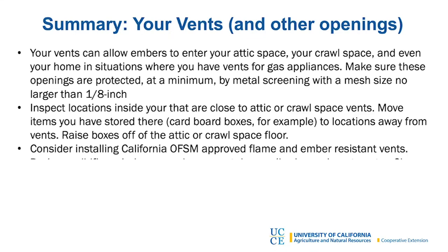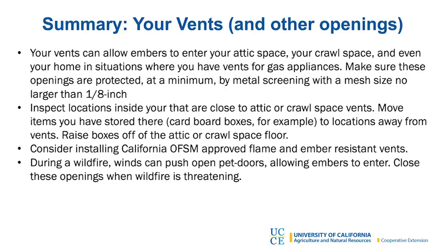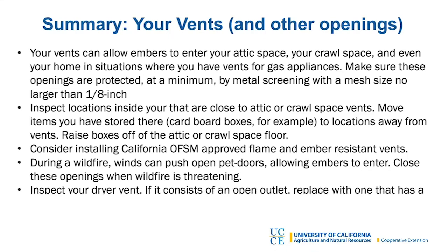During a wildland fire, remember that winds can push open pet doors, allowing embers to enter. So close these when wildfire is threatening so that they cannot operate. And then finally, inspect your dryer vent. If it has an opening that is open all the time, then replace it with one that has a metal flap, for example, that'll be closed unless the dryer is operating.